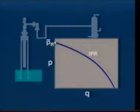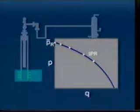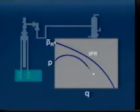It is convenient to use the IPR diagram as a basis for the description of pressure losses through our system. We can incorporate the pressure loss in the tubing into this diagram by using the appropriate correlations to estimate the flowing tubing pressure losses at different flow rates. The vertical axis is now pressure rather than P sub WF, and the new curve represents the tubing head pressure, that is, the pressure at the wellhead at the different flow rates.